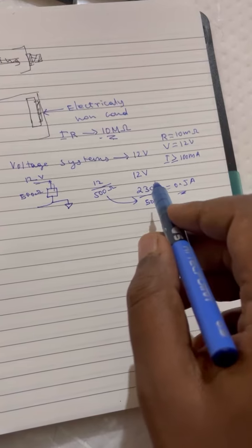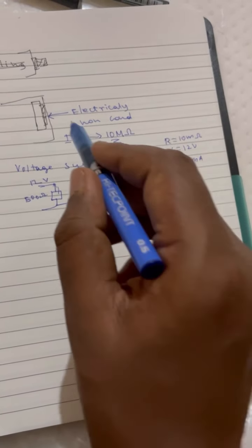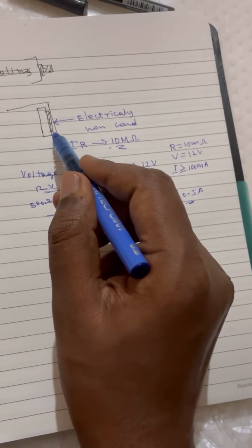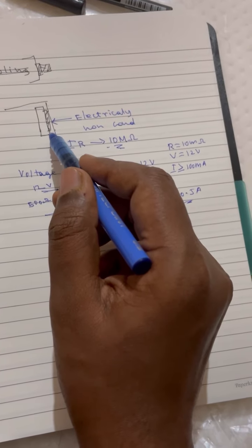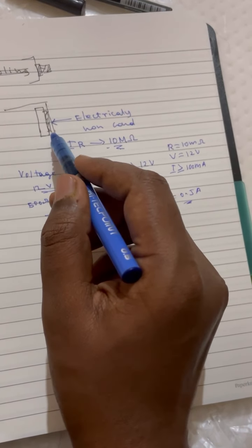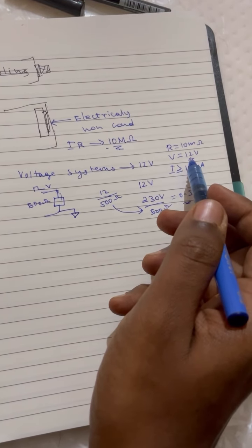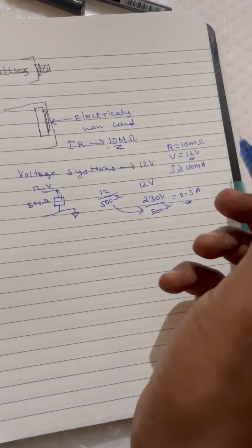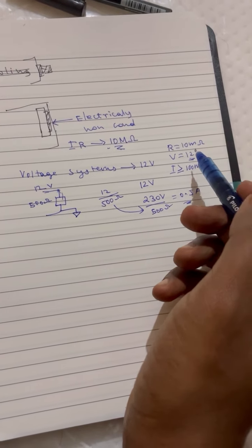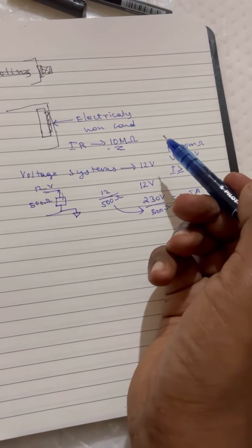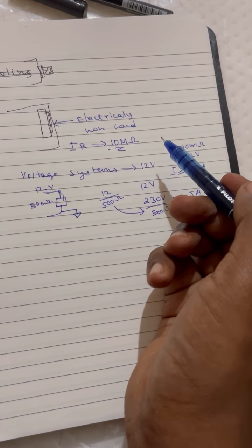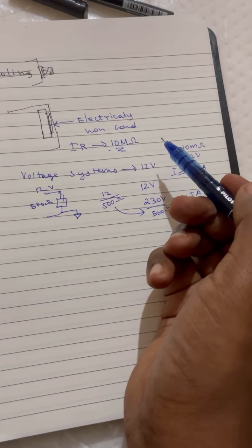So it's okay to choose an electrical system with a heat sink connecting to the chassis, but you have to be very careful about what kind of voltage level you are choosing. As long as your voltage system is under a safe limit, you are okay to have a different cooling or heat elimination system.